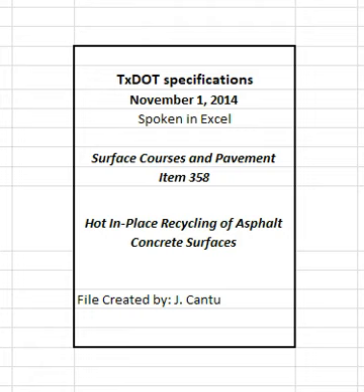1.2 Remixing. Remixing is similar to recycling with the addition of virgin aggregate or new hot mix asphalt, HMA, added to the recycled material. The materials are then thoroughly mixed and placed with a standard paving screed.